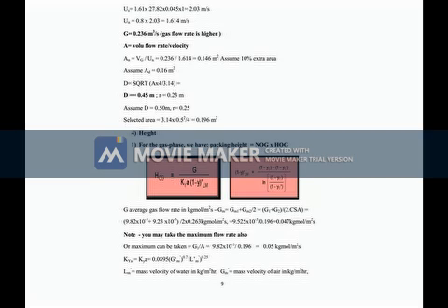That means X1, that is capital X1, the amount of ammonia that is going along with the liquid, that is solvent water, coming out of the tower is 0.0246. That is capital X1. You convert it into small x1, you refer to the notes: small x1 is capital X1 divided by 1 plus capital X1. It will be slightly less, small x1.